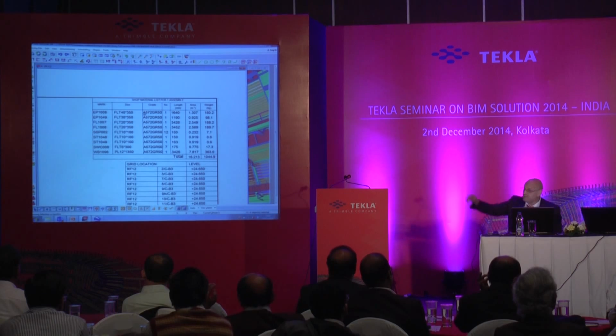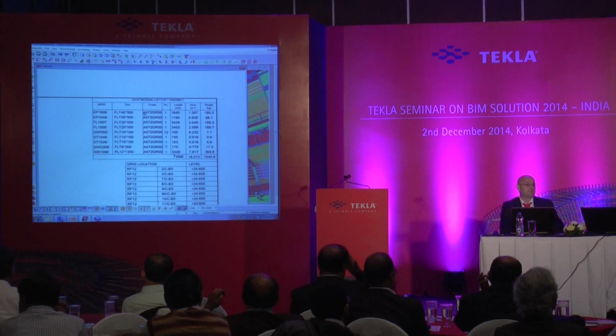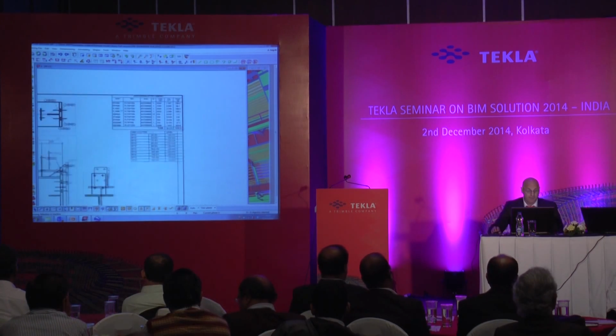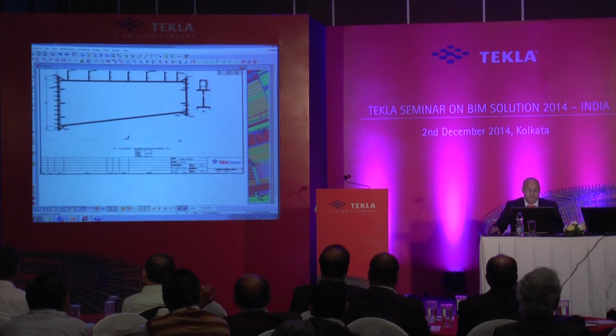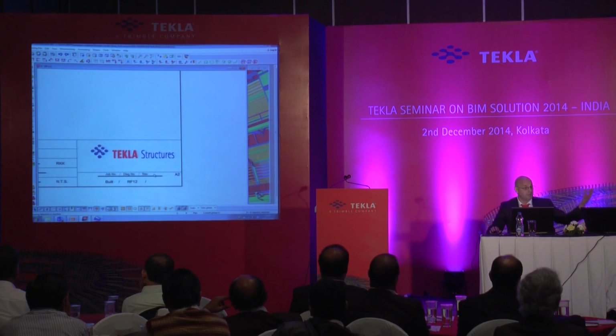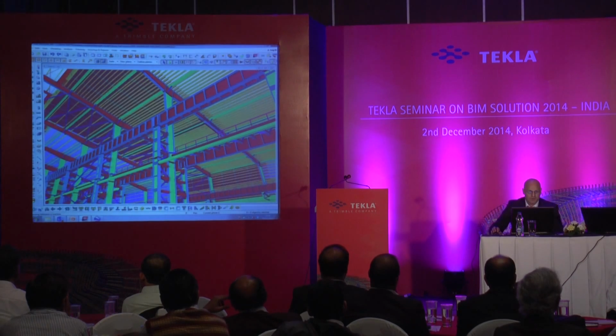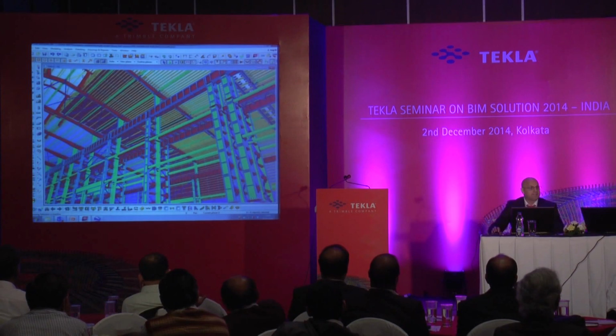You also get a full automatic bill of materials with weight and surface area. And the weights and surface area can be net or gross, depending on how you like to calculate that. Again, all the fittings, everything comes on there. The drawing borders, you can bring in your standard company drawing borders within there, etc. So we're creating those. As well as that, we're creating material lists from that structure.